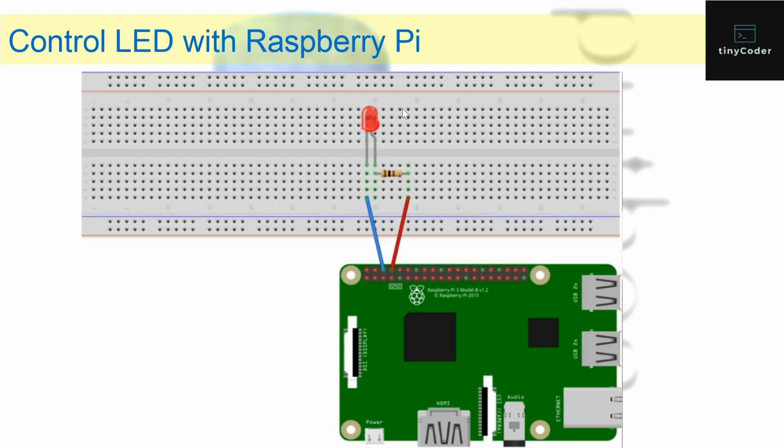And then this is the circuit of it. You can see that one leg goes to this blue wire, and you can't really see it, but it goes to GPIO21. Then there's another wire which goes through this resistor, which ends up going through this red wire, which ends up going to ground. So that's what the circuit basically is over here.